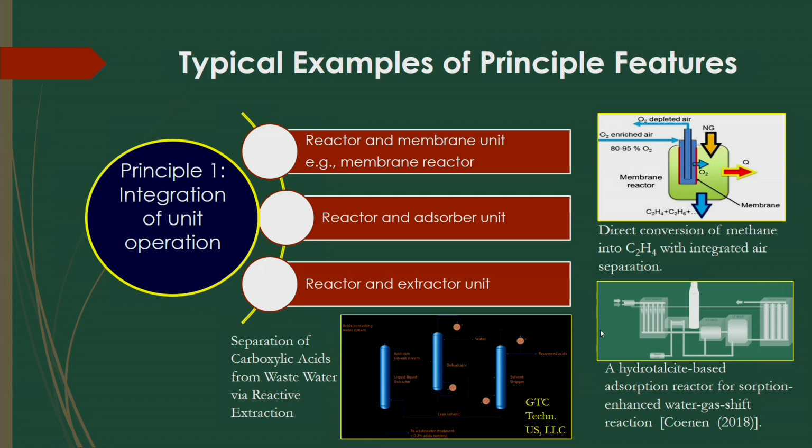Another example here is the direct conversion of methane with an integrated air separation process, and some other examples like the hydrotalcite-based adsorption reactor for the separation in an enhanced water gas shift reaction, where reaction as well as adsorption both happen in a particular operation. So, it is an integrated operation. That is why we can say that one of the important features of process intensification is called integration of unit operations.